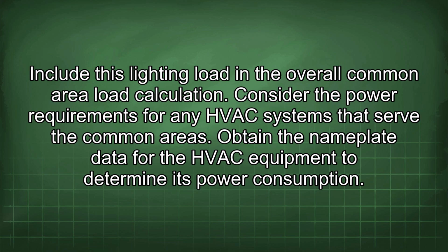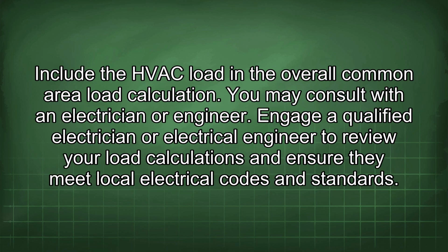Obtain the nameplate data for the HVAC equipment to determine its power consumption. Include the HVAC load in the overall common area load calculation. You may consult with an electrician or engineer.